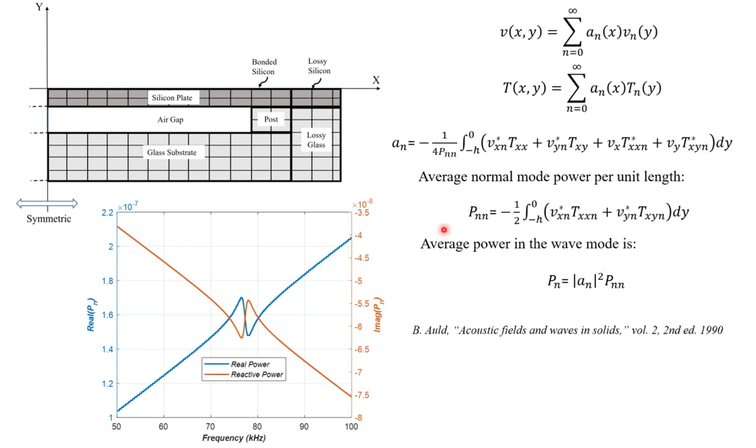So let's see. Here I have an axisymmetric model of a CMUT. It's a typical wafer bonded CMUT. You can see the dark regions. These are the meshed elements of silicon which are bonded on a glass, and you have a glass post, and that's the interface at which the silicon plate is bonded. And then you have the etched cavity, which is an evacuated cavity. It doesn't have any air, it's vacuum, and the silicon plate is suspended over it.